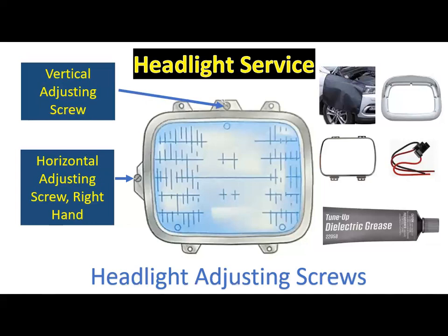If not, then you have to recheck. You have to check the connector. Maybe the connector is still loose or something. Install the headlight bezel and retaining screws and check and readjust the headlight aim as necessary. But if not, then you don't have to do that.